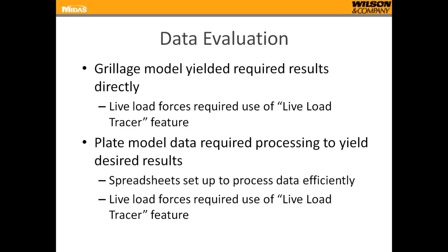This section is what I was doing a lot of the time for this project. It's the data evaluation. The grillage model yielded the required results directly. We were looking for shear and moment. That was a direct output. We were looking for displacements. Again, that was a direct output. The live load forces, in some cases, required the use of the live load tracer feature.